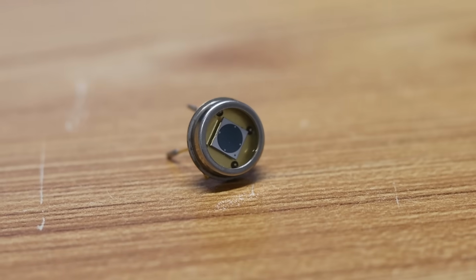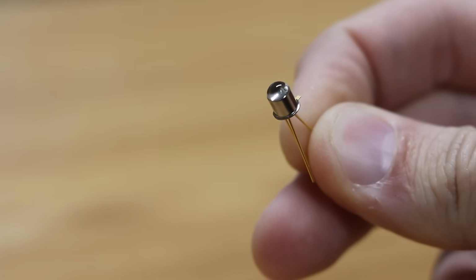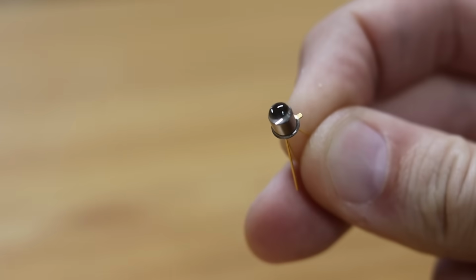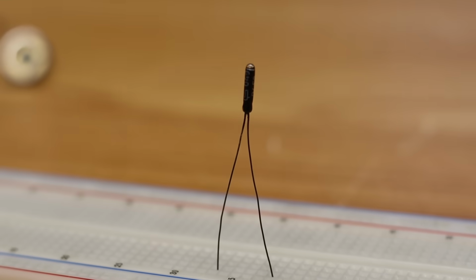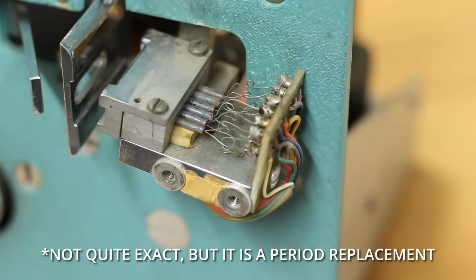If you more strategically pick your semiconductor material, doping material, size of the depletion region, and maybe even add in a lens to direct the photons onto that region, you can make a much better photodiode, like this 3F42 photodiode right here, which is absolutely tiny, but this is the exact photodiode that the Bendix G-15 uses.